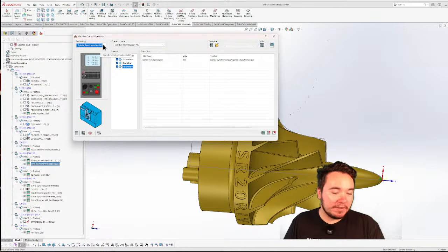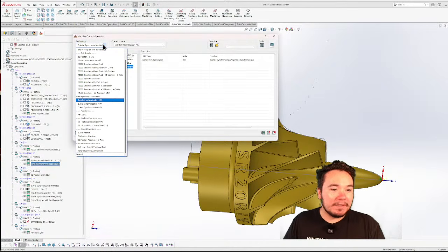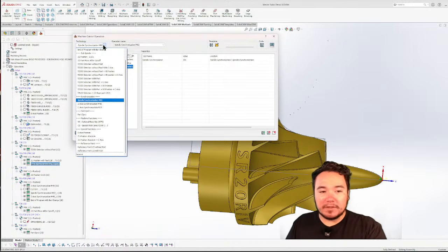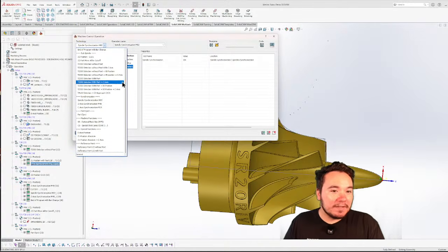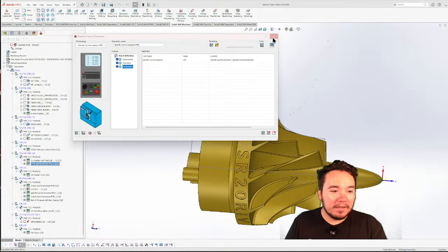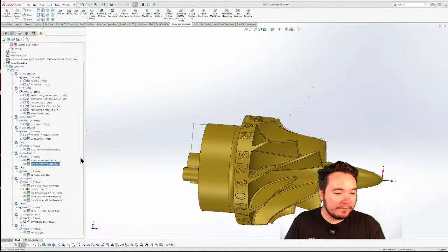This is another one, just like the T2000, that you're just going to grab, and again, it's going to be machine controller specific. You know, what M codes it's going to be calling out to be doing this. So this one's going to be M82 that syncs the main and sub at the same spin rate.